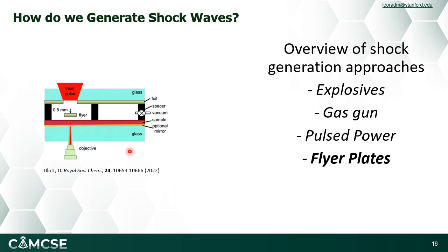In other cases, we have slightly smaller facilities that allow us to look at plate impact. There are laser-based versions of this that, at much lower pressures, look at, say, a glass substrate with a metal foil on it. And then they can use a laser pulse to, in a very small amount of time, generate a plasma that launches our flyer plate loose from the glass substrate and pushes it very quickly at high velocities into the sample material underneath.